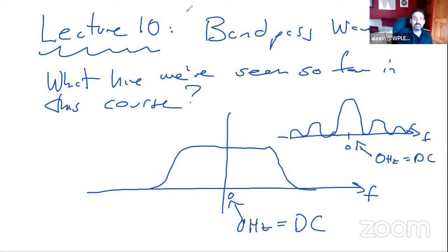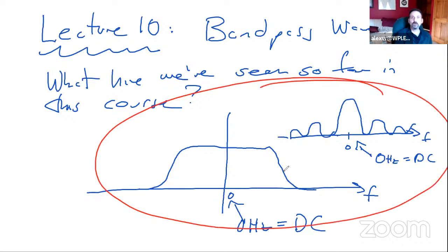So these things we've seen so far, and everything else, the line codes, PAM, PCM, all that jazz, are all at 0 hertz. Everything is centered at 0 hertz. Maybe we did move things to some minus fc and fc, but it's a relatively small modulation to those frequencies.